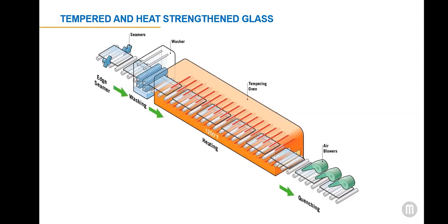The breakage characteristics allow the glass to remain in the window frame as the large pieces support each other in the opening. Heat strengthened glass also has high thermal strength like tempered glass and is resistant to thermal stress breakage associated with the high performance tinted or reflected insulating units.